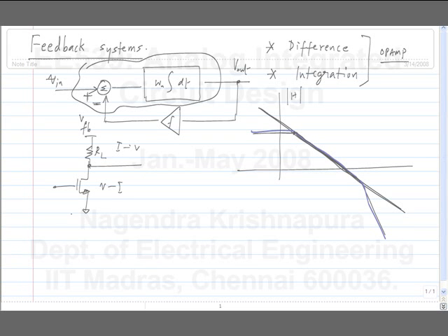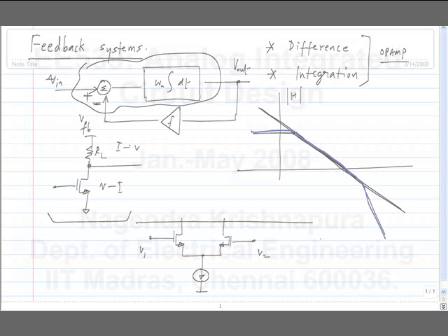Now, a differential pair is nothing but a common source amplifier, some differential version of that. So, that also does the same thing. This part of the circuit, the tail current source and the transistor give you a current that is proportional to the difference voltage. So, this part gives you V to I, and that I can be passed through a resistor to get you a voltage output.